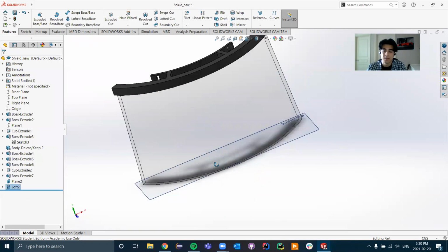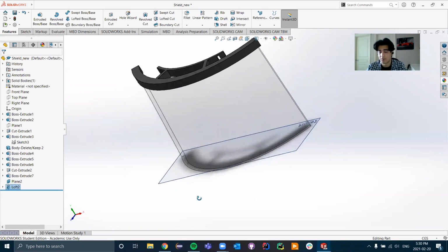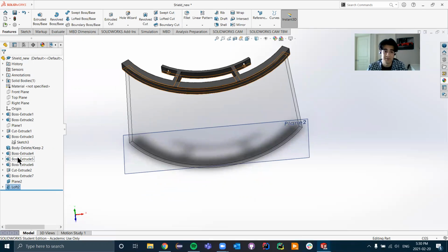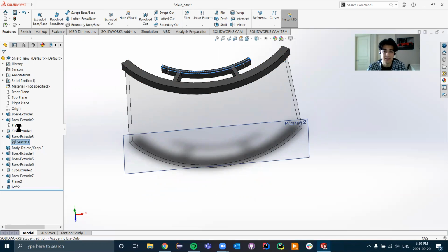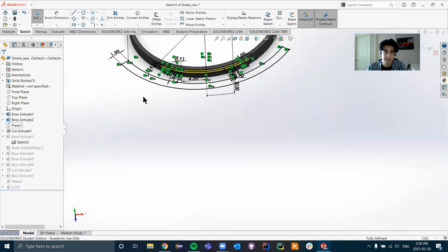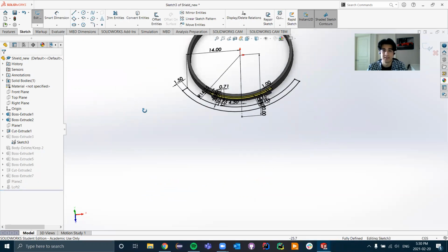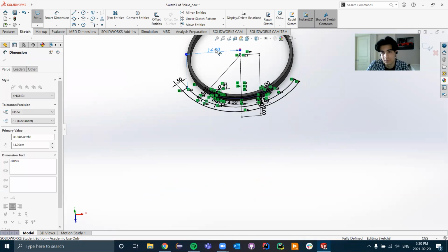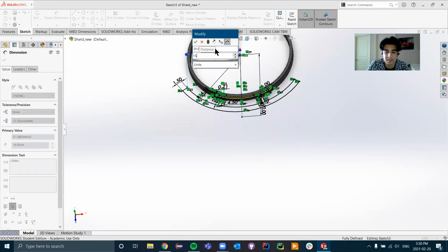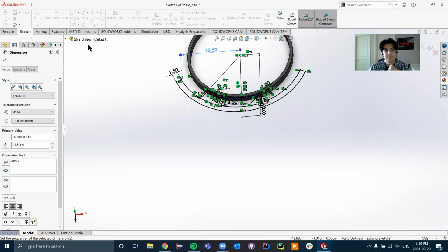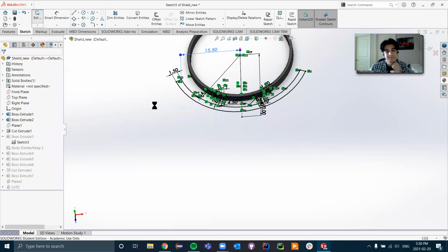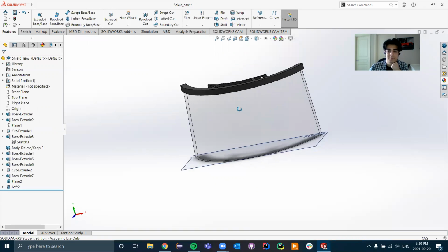Looks a bit better. And if you want, again, we can reduce or increase the radius. It's completely up to you. Now see if I try to do what I did before. So if I go into sketch 3 and edit the sketch, and say we increase that radius to, let's say, 15, now what we wanted before, 15 or 16, let's do 15.5, a compromise between the two. And then press exit. Give it some time. You'll notice everything updated accordingly.